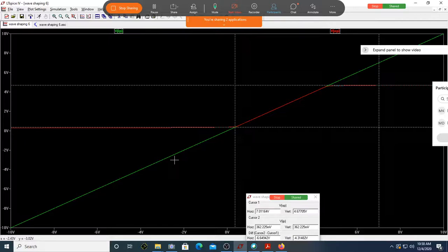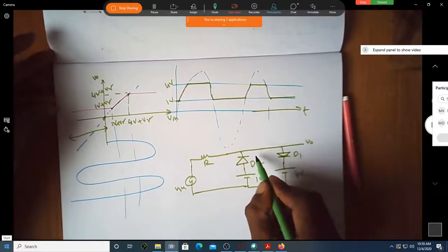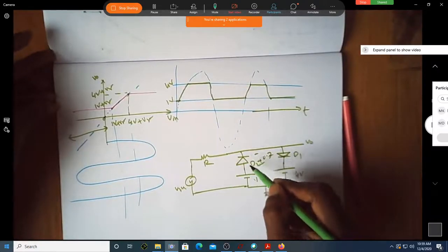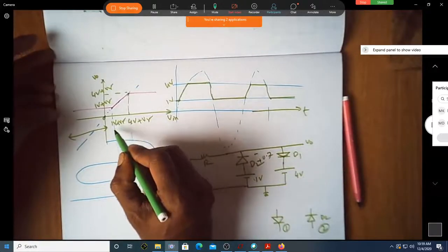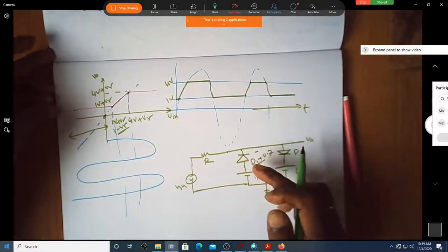One difference I'll just make it here. Okay, it's good that I could make you people observe. So this is 1 volt. This is actually minus plus 0.7. So this will happen. Okay, what is the effective voltage now? This will not be 1 plus V gamma. This is actually 1 minus V gamma, because you have the battery and these are in opposite direction.